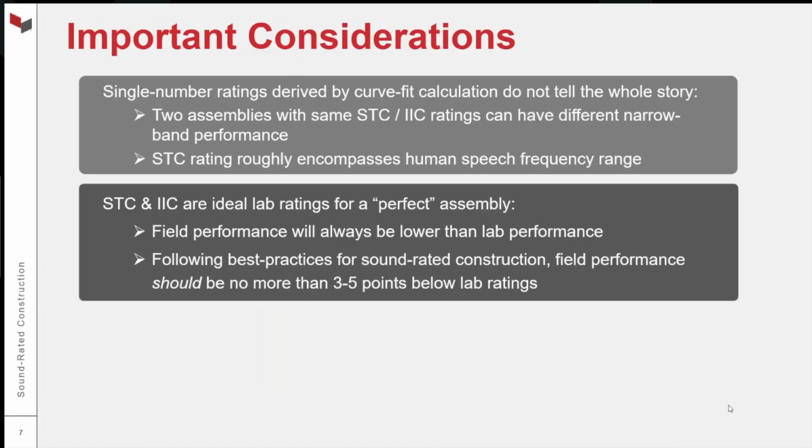Another important consideration: STC and IIC are ideal laboratory ratings. When we build these assemblies in the lab, they do not have any penetrations, no outlet boxes, no light switches. They are, for all intents and purposes, perfect. So that laboratory number that you see published in whatever guide or literature represents an ideal assembly. Obviously, in the field, conditions are usually anything but ideal. So you should always expect field performance to be lower than laboratory performance.